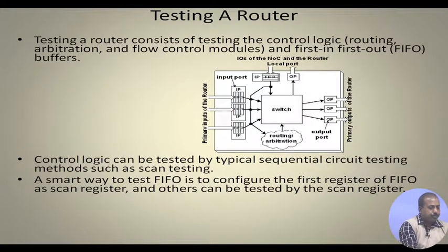Now, also there is arbitration. If there are multiple packets which are asking for the same port, then I have to tell which packet will go first, and the others will be waiting. Similarly, through this switch at one point of time only one packet will go. So, we have to see which one will be picked up. Maybe we follow a round robin policy. One of the packets is given the green signal to proceed through this switch.